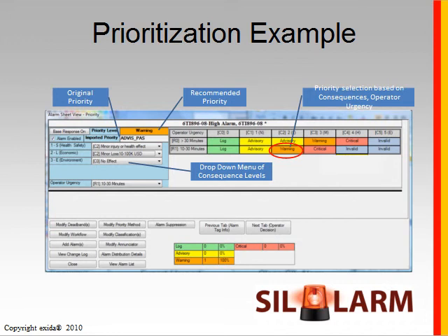And those might sound like conditions or areas that you would consider during a HAZOP or a LOPA. And if you make that connection, that's correct. What we actually want to do is, when possible, use the same consequence matrix that exists for those activities and use that for alarm management as well to help us set the priority of the alarm.